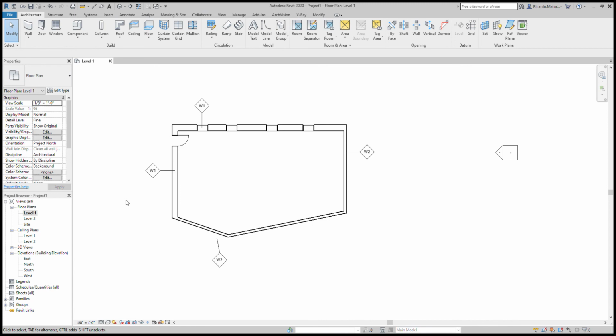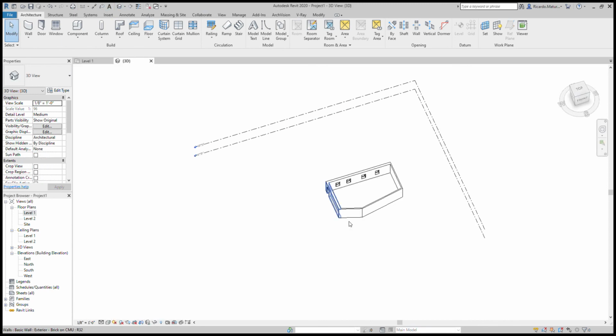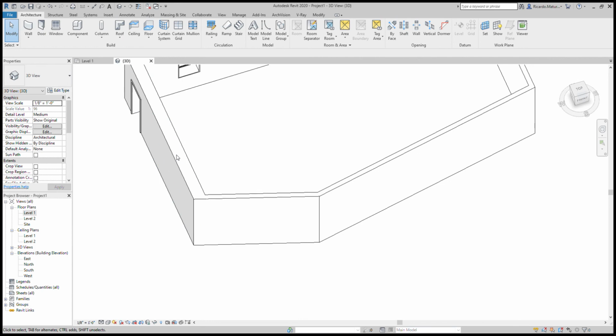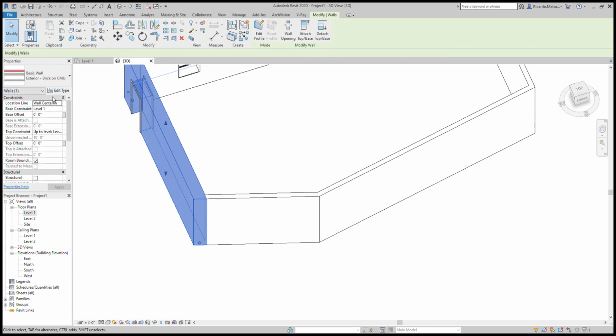So going back to the wall properties, you can say we take this wall, and if you go to the type, you can say here under structure, you can see all the definitions of all the layers that you saw. And you can adjust, say you can change the gypsum for say a 1/2 inch, and then it will automatically update all the wall types.